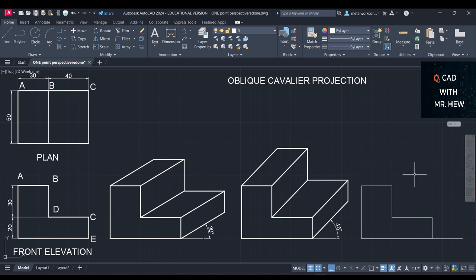Then now you're going to draw the lines at an angle. The angle will be 60. So we're going to go again. The length of the line is 50 and the angle is 60 degrees, right? Then the line we drew a while ago came from this point.